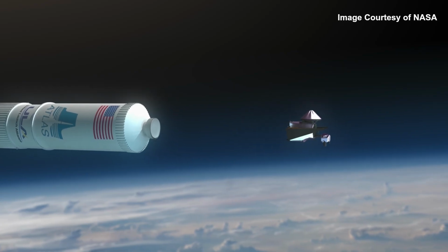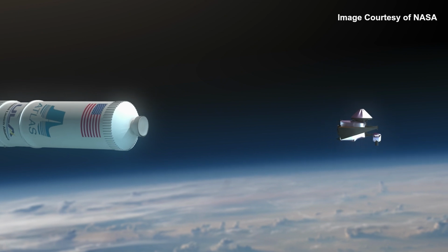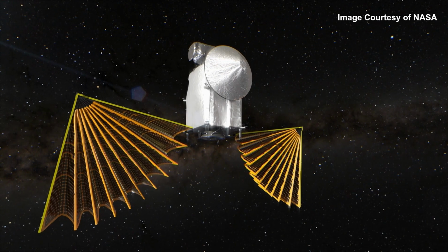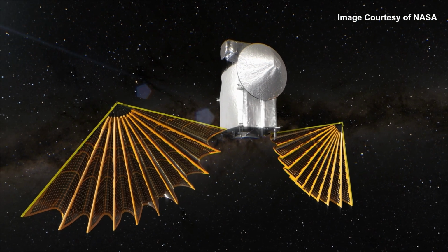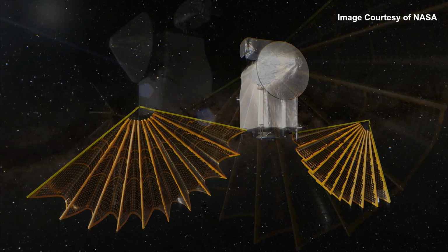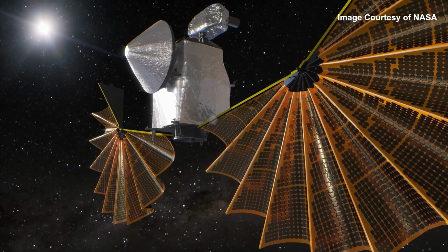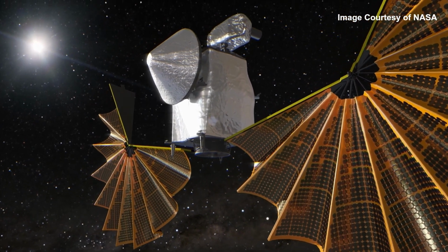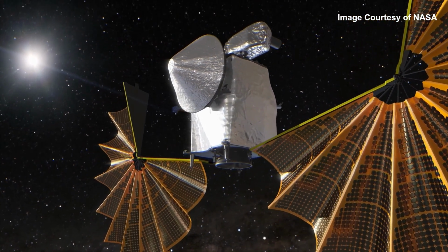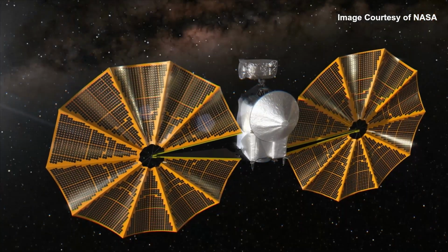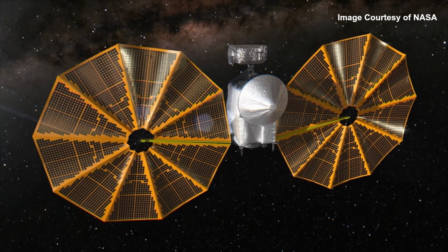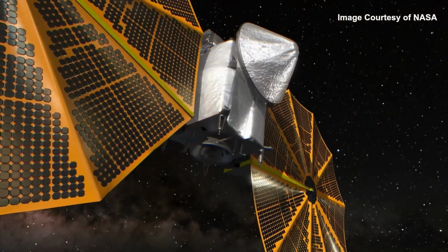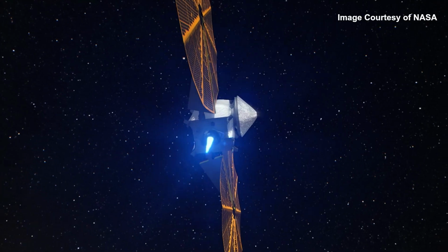This can happen when we're talking about very dielectric heavy materials. For example, the Lucy spacecraft has a solar cell that is very heavy in terms of dielectrics and is very sensitive to the amount of radiation that is present. And so depending on the type of environment that you're exposed to, if you're, for example, in low Earth orbit or in GEO, the response and the amount of charging inside the cell is going to be very different.